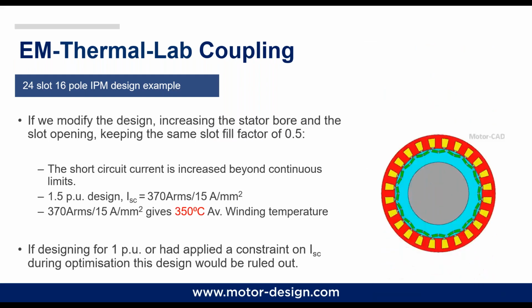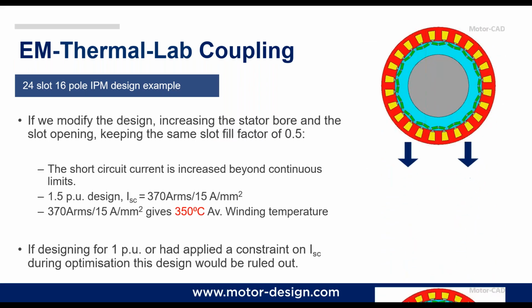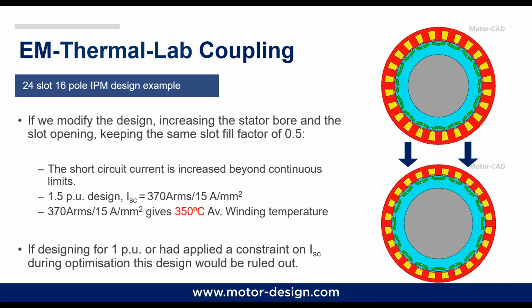So here, what I've done, I've taken that design, I played a little bit with this geometry. I increased a little bit the stator bore, I opened up a little bit the slot, I changed a few parameters as shown here, but keeping pretty much all the other design parameters consistent, including, for example, the slot fill factor of 0.5.